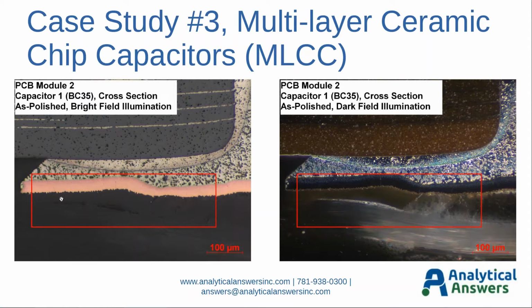A little bit more about that defect that I observed. It's a delamination or a void here between a glass fiber rich region and a resin rich region near the surface of the PCB. It's actually caused this land or this pad that the MLCC was attached to buckle. This most likely occurred during the SMT processing when some thermal activity occurred during that processing.